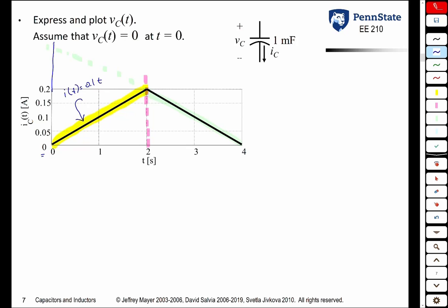The y-intercept would be at 0.4 amps. So this line segment, I of t, is going to be minus 0.1 t plus 0.4. And I guess these are both amps. Once again, why is it negative 0.1? Because that is the slope.